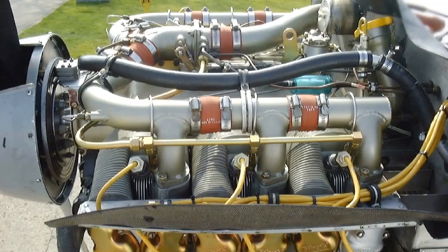The type of fuel injection system usually used on aircraft piston engines is the low-pressure, continuous flow type of indirect fuel injection. Although this type of system is fuel inefficient, it does eliminate the need for complex injection timing devices and spring-loaded injector nozzles. The price that's paid for the simplicity of the system and its relatively trouble-free operation is the comparatively inefficient way in which it uses fuel.